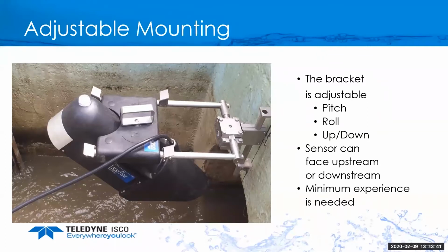And one thing that's kind of good about these things as we go down the road is we're finding that you really don't need a lot of experience to install these things. Normally, with any non-contact, you're going to mount it roughly right at about the crown of the pipe. So you need to just drill a couple holes. You can put a level on there to kind of get it where you need it to be, and you tighten the bolts and away you go.